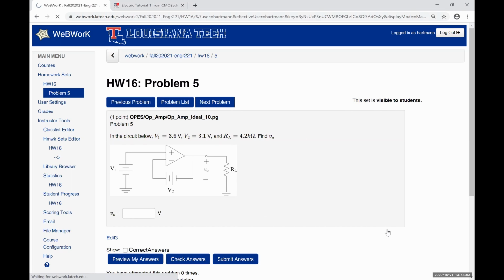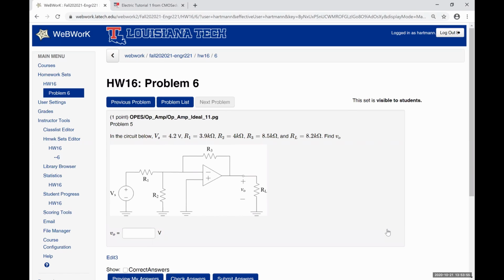This last one is the first one that's actually even remotely close to the level of difficulty of the questions that I would prefer to ask. What's the voltage present at the non-inverting input terminal? 0. So that means the voltage present at the inverting input terminal is also 0, right? What's the voltage drop over the resistor R2? It's 0, because 0 minus 0 is equal to 0.